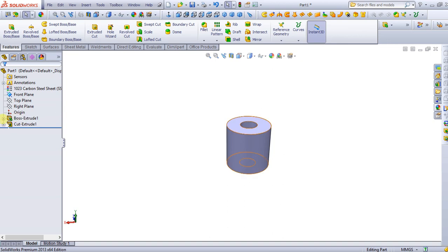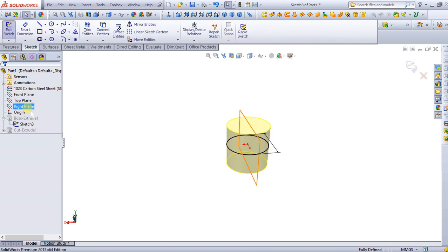You come to this plus, click on that plus, and it gives you access to the first sketch you made. You click on it and come to edit sketch. You can edit sketch plane, suppress, roll back, make normal, zoom, hide. Assume you want to hide that portion, you hide it there. Now we want to edit our sketch. You click this edit sketch, make it normal.